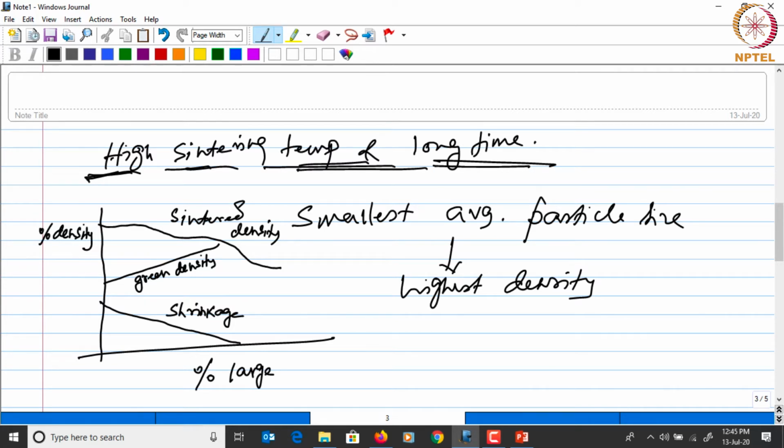The trend, of course, can change depending on the material that we are talking about. Here, this was an example for iron powder, having two dominant sizes, one bigger, which is 66 micron, and the other, the smaller size, let's say about 4 micron. Okay, so it has a mix of large particles like that and also smaller particles, where there is a significant difference in the size.